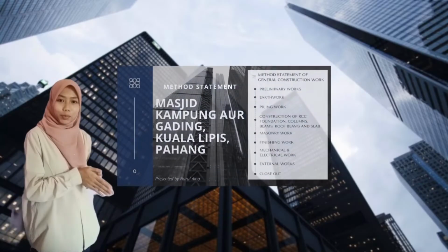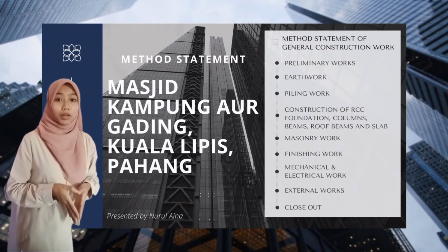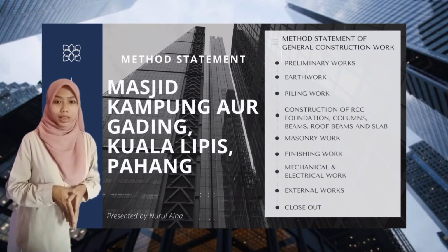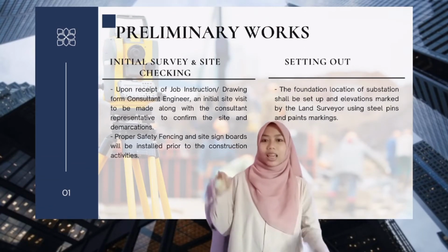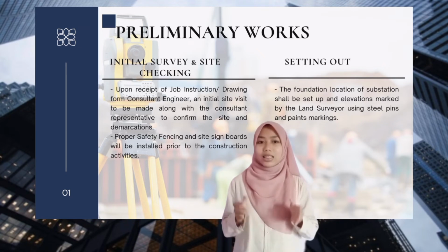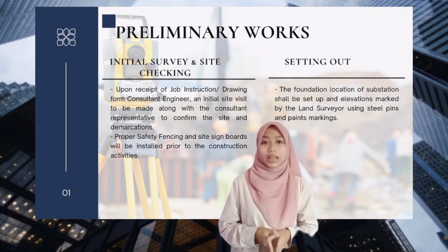Thank you. Assalamualaikum and hi, I'm Nura Aina Binti Hanafi. We'll continue with the method statement of general construction work in our project. First, let's look at preliminary work. We have initial survey and site checking and setting out, which is an initial site visit to be made along with consultant representative to confirm the site and delimitation.